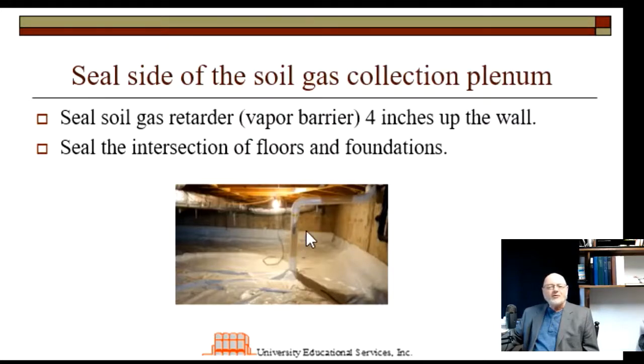Now here it's run up what appears to me to be more than 4 inches. And so that's just a picture to show you what it's going to look like when you do it. And then where the floor meets the foundation, you need to seal that as well. You can't afford to leave any place for the radon gas to come up and come through the cracks and spaces of the foundation. So that's got to be as close to airtight as you can make it. And so that's the reason for these remarks.